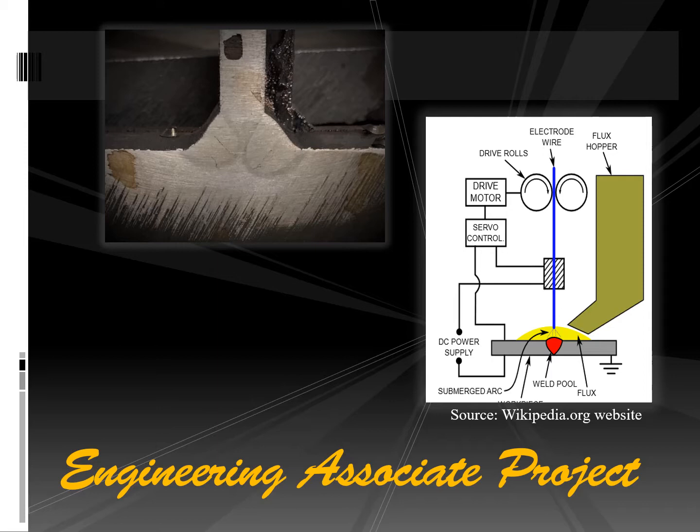My engineering associate project focuses on the capabilities of phased array inspections being carried out on partial penetration T-fillet welds, specifically those which are welded with a submerged arc welding process. The sub-arc method is basically an automated welding technique which uses a granular flux to shield the arc during fusion.